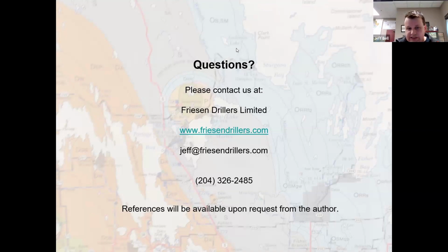We have had no success at all in doing test work or anything with well-to-well heating and cooling systems for industrial or anything in any of the screened units or any of the unconsolidated geologies. Sand and gravel, like screened water wells, we don't tend to see a lot of great results in that. So the formation that we tend to work in the most often is the bedrock formation. So most of the common well-to-well systems tend to involve something to do with the bedrock.